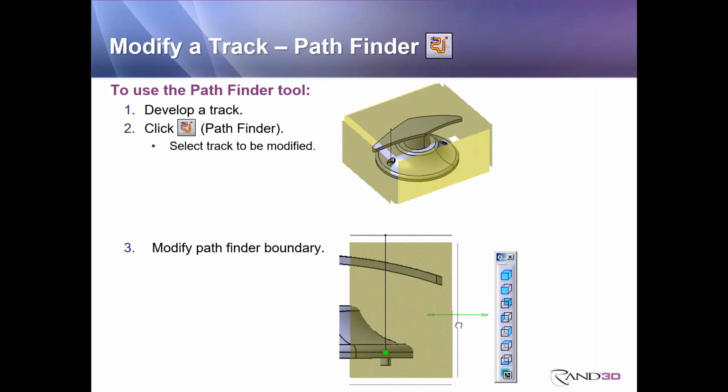As soon as you do this, you're going to see a yellow box around your environment. That yellow box is the bounding box. The space that the yellow box creates is all of the potential locations that you're allowing the object to move to in order to find the path around the obstacles. So you probably want to do a little bit of due diligence here and not allow it as much space as the entire environment, as you can see here, because we don't want it to take time bouncing over here at the corner. So try and adjust this so that you're giving it a smaller space.